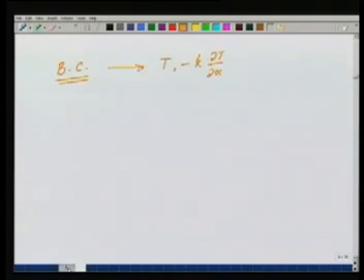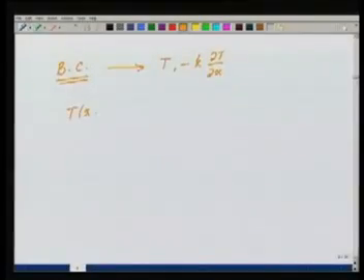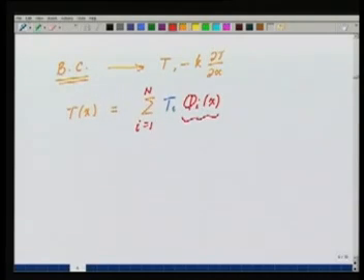So the basic idea is that I will take the same representation in space for t as we had been doing for the static problem. So t as a function of x for the static problem was the sum of some coefficients ti times phi I of x, I equal to 1 to the number of degrees of freedom n, where phi I are our usual C0 basis functions.